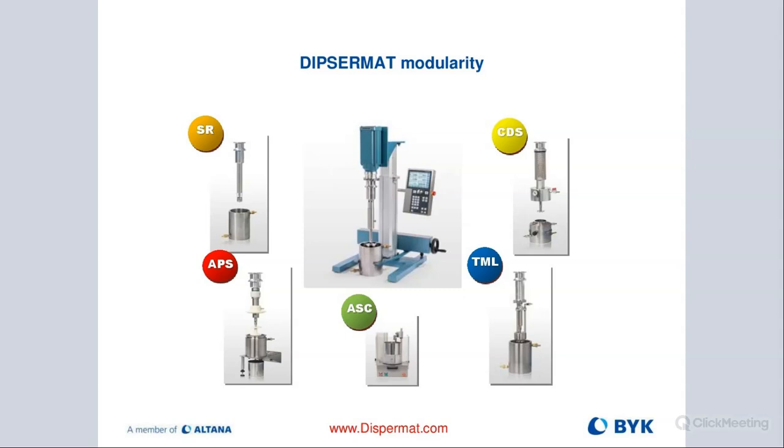That's kind of like a quick change system, how it can be attached in less than 1 minute with this bayonet-style clamping ring. You remove it and you turn this assembly 180 degrees. And now you're able to just pop on a basket mill. And then you're off with the same machine you're milling. So basically, you need less desk space. You can mill on the same machine that you did your pre-dispersion. And that is a huge advantage. You don't have to learn a new control panel.